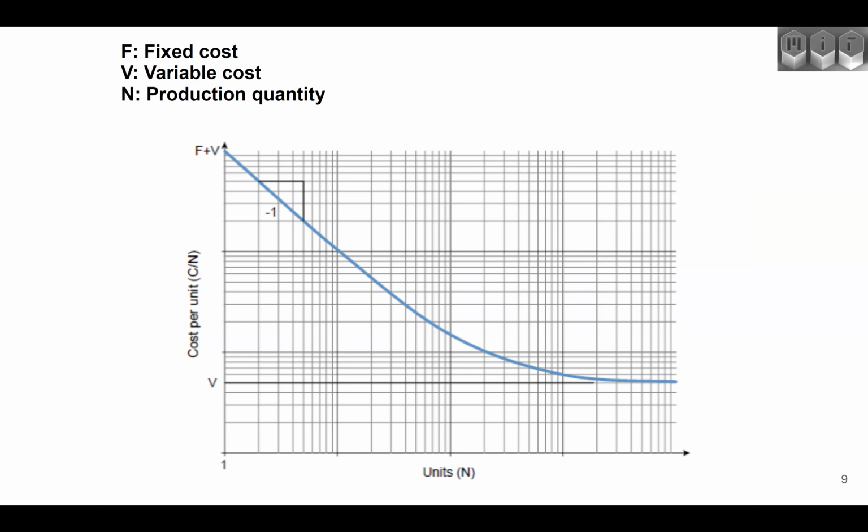But a fixed cost is something that you are required to pay, but often we call this a one-time cost, right? Or it's a cost per a large number of units, and it's unavoidable. But it doesn't necessarily scale, meaning it doesn't increase linearly as the number of units increases. An example of a fixed cost would be your machine. You buy the machine once, and then you make however many units you can make until that thing runs ragged and you have to replace it. And in injection molding, that fixed cost would be, say, the cost of the mold.